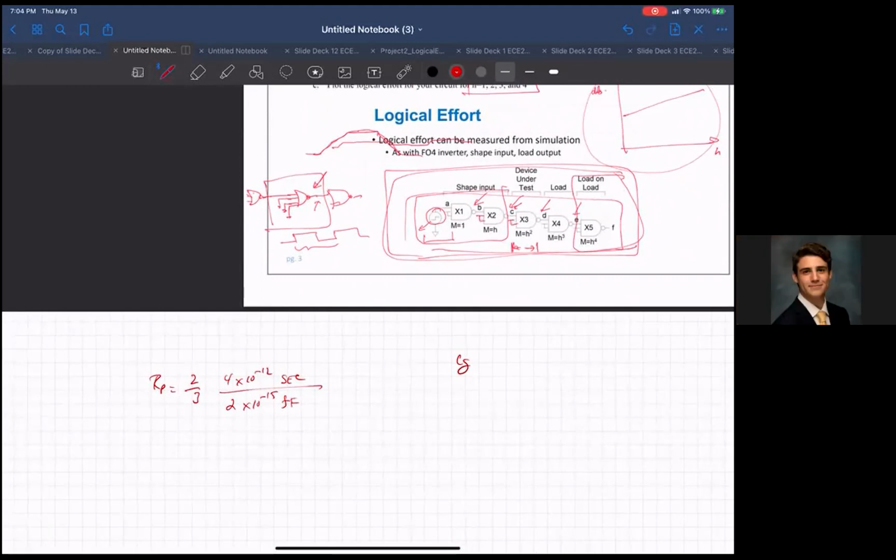No, that doesn't seem right. Because if I have 80 femtofarads for my C_G for the previous number, and I divide that by the 28.8 microns, then I get about 2.7 times 10 to the negative 9 for my C_G.